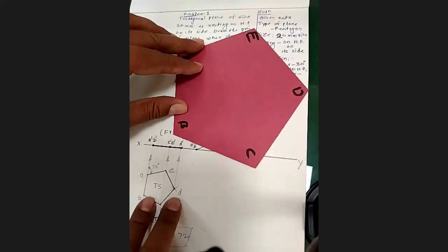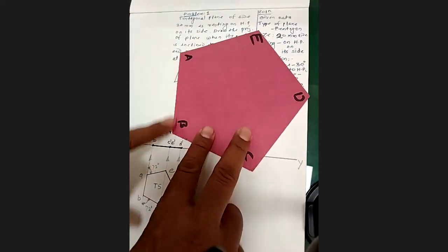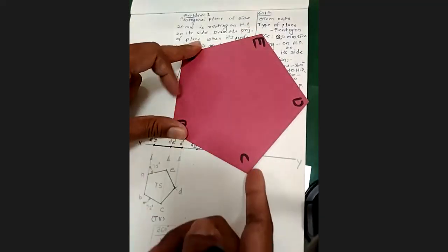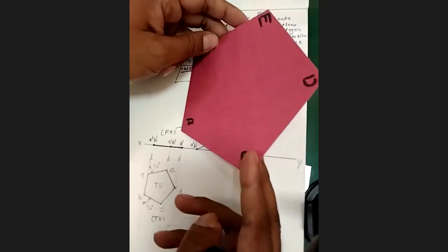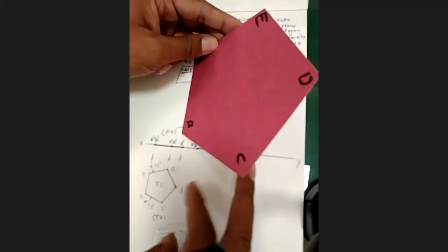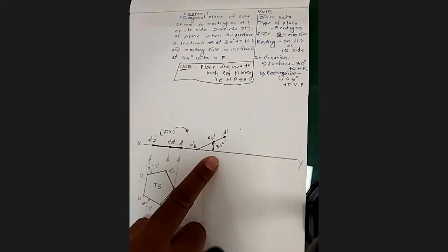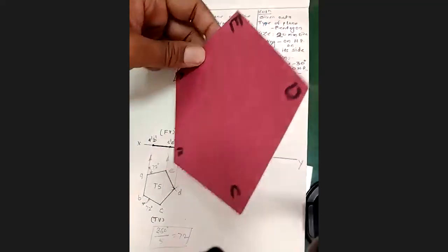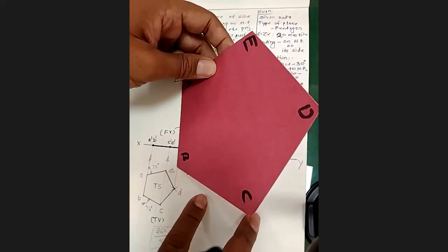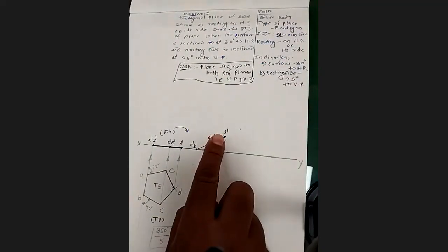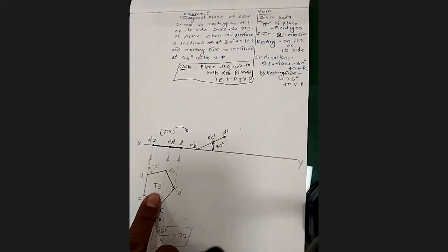In the first stage, we completed this top view, considering it is on its surface and side, on the left side. We completed this true shape. Then we drew the front view, and we got the line view. Now we will be turning this plane, making an inclination with the surface; we are just rotating this line view as per the given condition, that is 30-degree. Now, whatever front view and top view we get at this stage, we will get by taking the projections from this front view and the previous stage top view. How we will get it, we will discuss now.